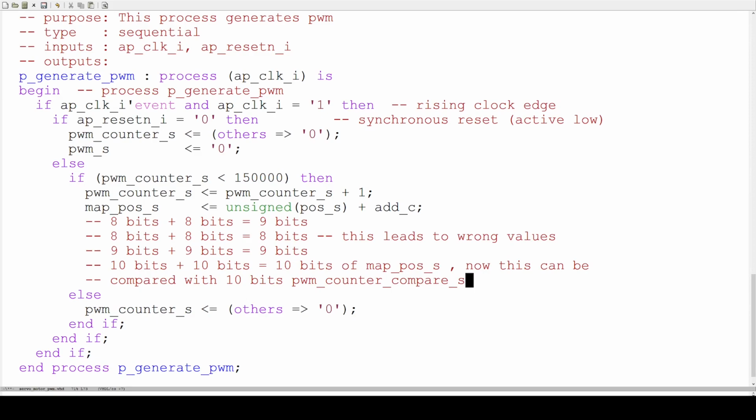So this is to make it easy, and this is a very common mistake a developer makes, and it's very hard to find sometimes because the bit resolution is lost somewhere; we can only come to know after simulating the specific values or the higher MSB values. So always try to put more effort on bit depth while doing arithmetic calculations.